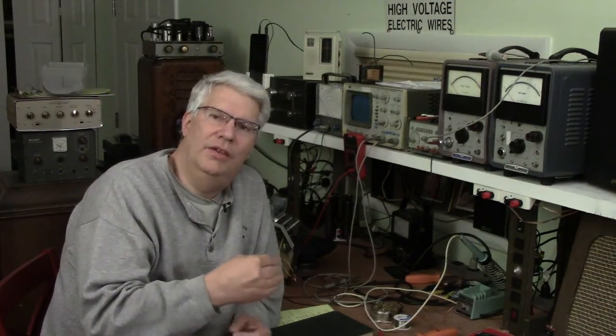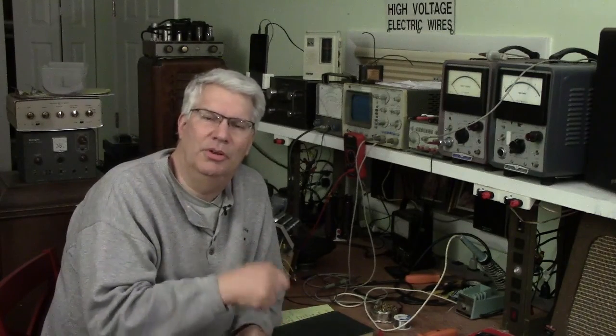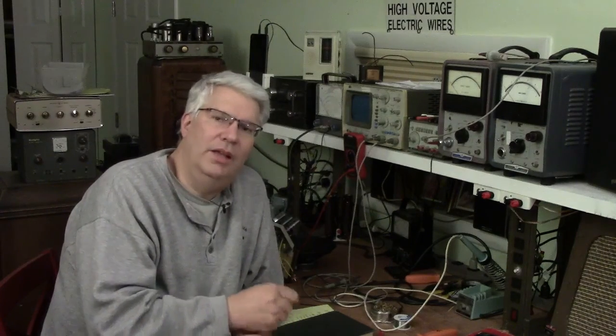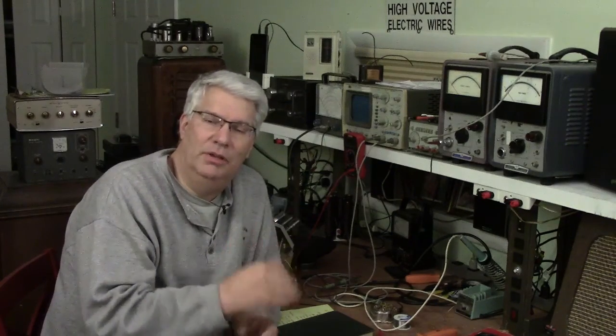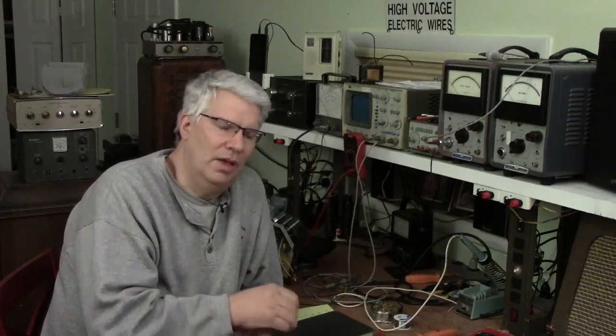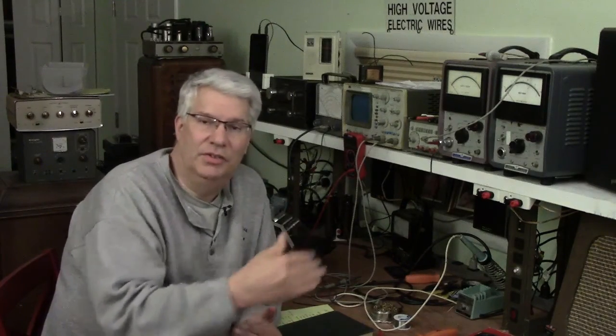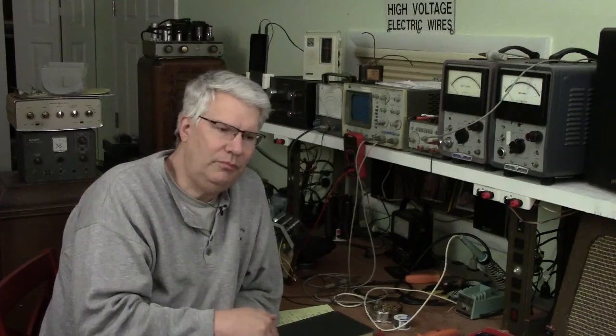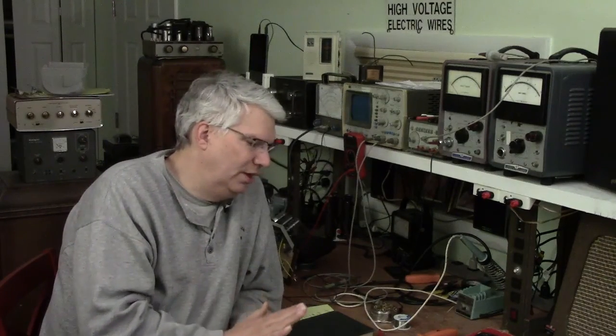Then we looked at the option of changing the turns ratio on the transformer or the speaker impedance, which is probably the easiest thing to change, and the anode plate current and voltage. If we change those around, we go from 400 milliwatts, 0.4 watts, up to possibly 2 watts when running this one tube in triode mode. That's quite a significant difference, 4 times the power. But all that's unrealistic for several reasons.